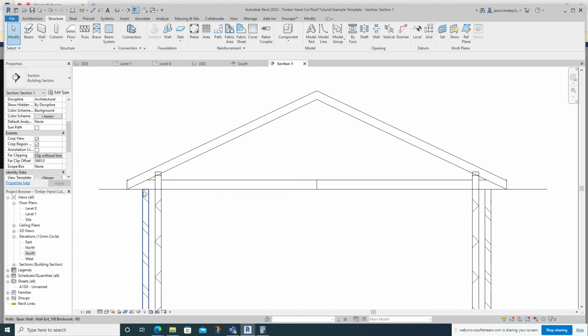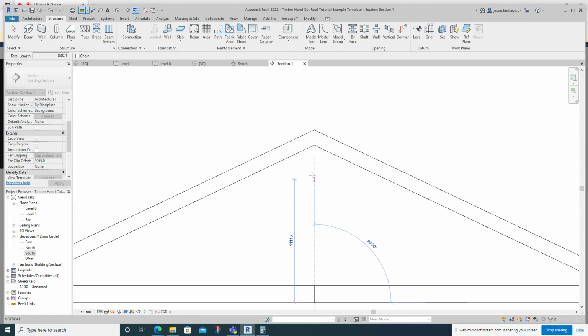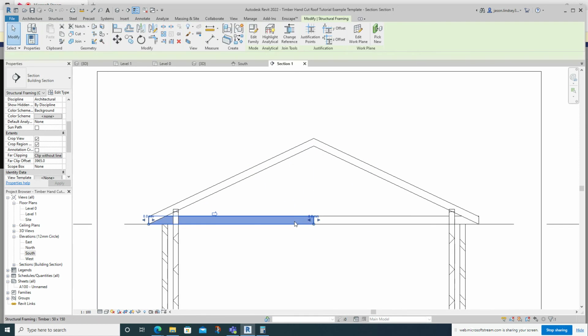So when I lift this one up, it'll rotate on that point there. I do need to measure how high I need to go, because it doesn't do it in degrees, it only does it as a measurement. So from the bottom there, bring that up to the top there, that's 1422. I just need to remember that. So with this here, click on that. This was where I started, so that's my start level offset. This is where I finished drawing it, so that's my end level offset.